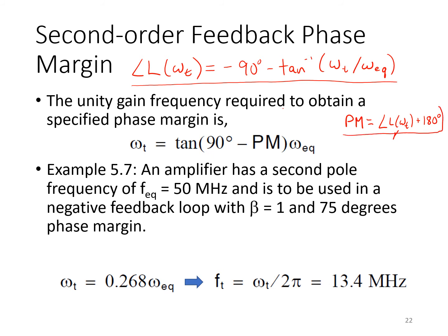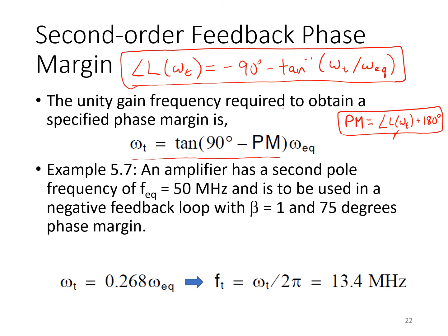And so using these two expressions, combining and rearranging, we get this expression here that relates phase margin to omega EQ and omega T. In fact, it's useful to rearrange this a little bit further and relate the phase margin in terms of the ratio of omega T over omega EQ.